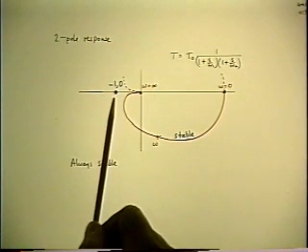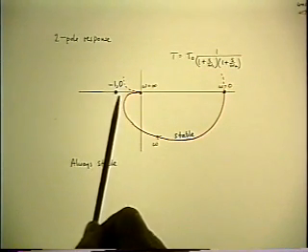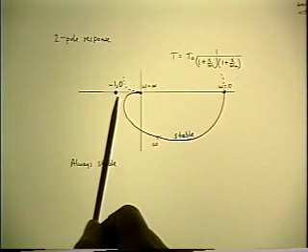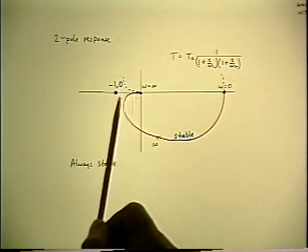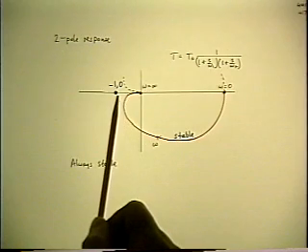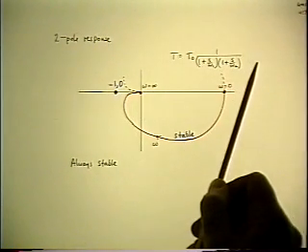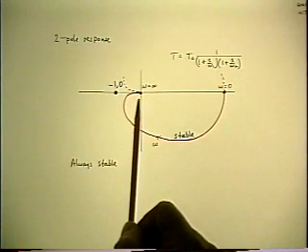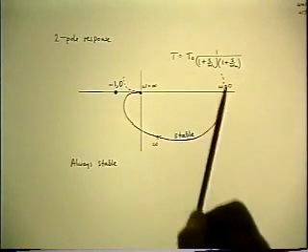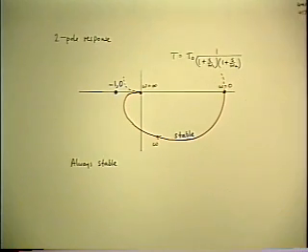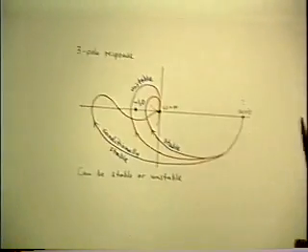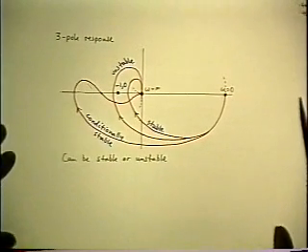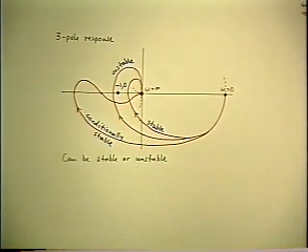It could get very close to it, but it will never get to the -1 point, because that would require the magnitude to be finite and the phase angle to be 180, but with two poles you don't get to 180 until infinite frequency when the magnitude is 0. So still, a two-pole loop gain is always stable. It's when you get to three poles and up that you have possible problems.